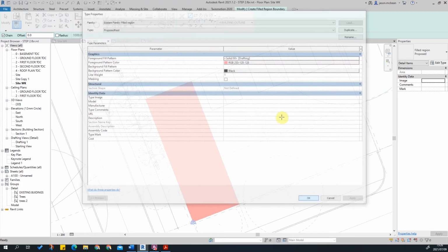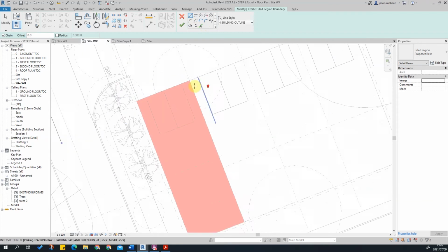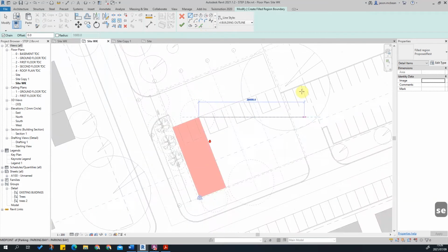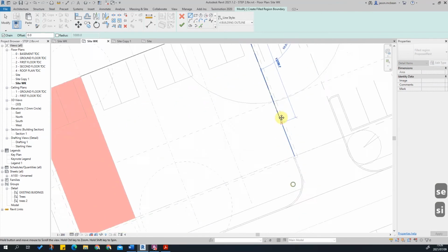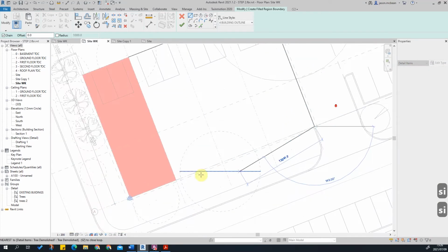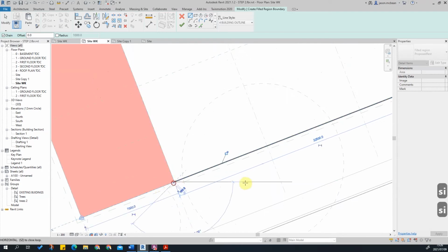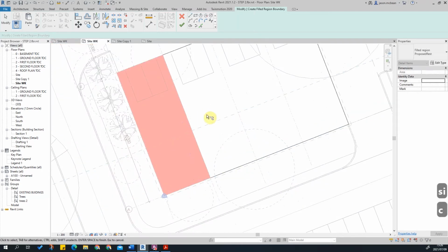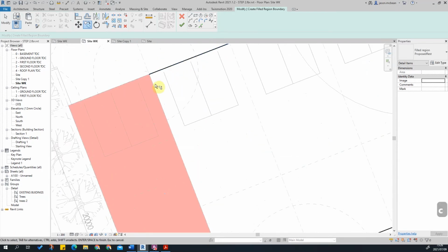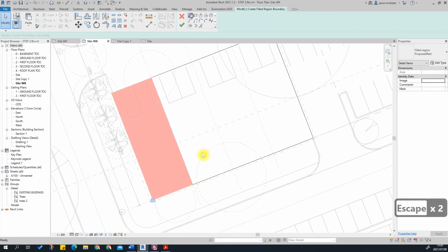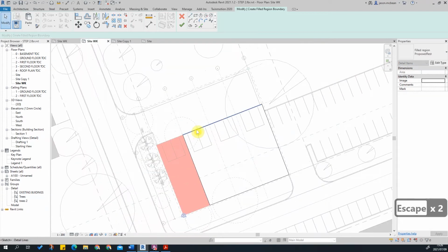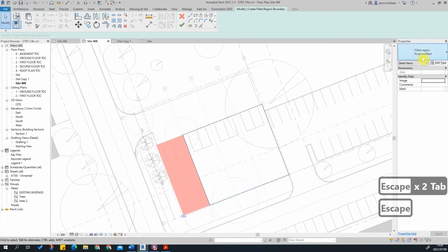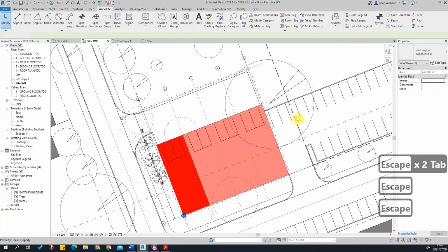Press OK. Now I'm simply going to use a line command. So snap end, snap. Here we're going to go SI, snap intersection, snap end or intersection, and then C for close. Okay, you can see here you can close the command as well. It was the wrong command, so let me just do that again. So from there to there. Now just make sure, tab, make sure it's all one closed set of line work and it's a proposed rest. Now if I finish the command now, okay.